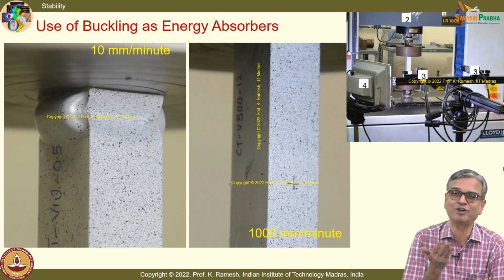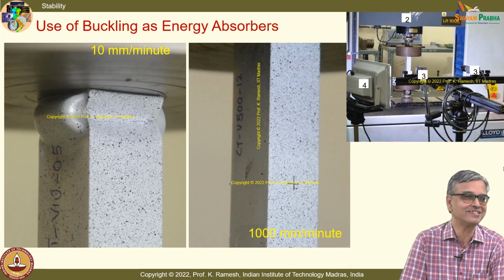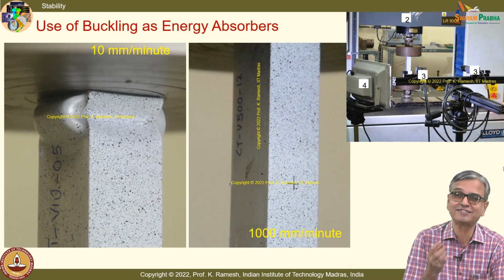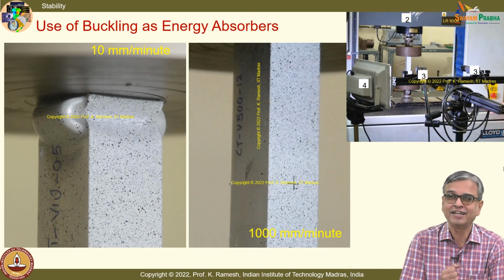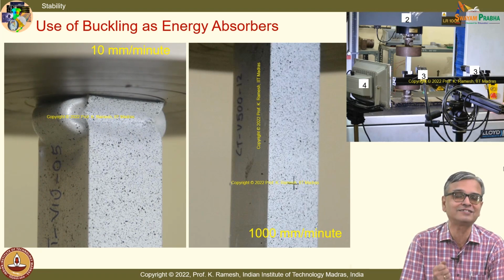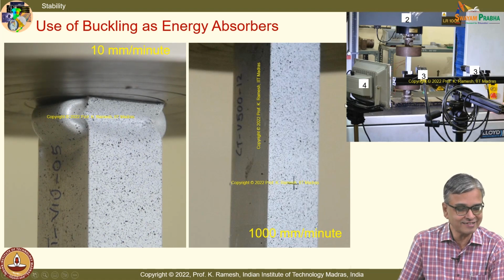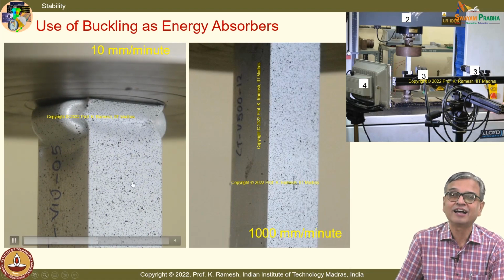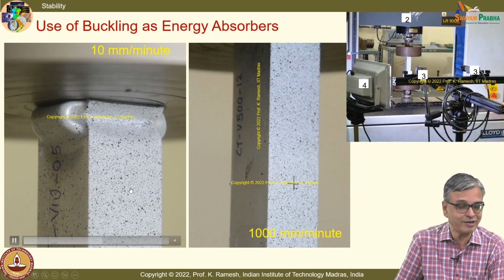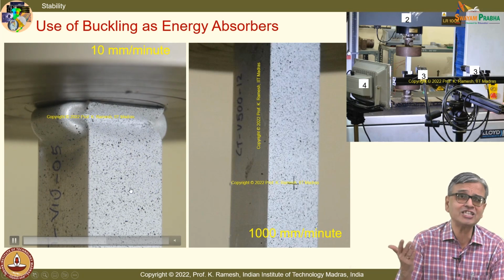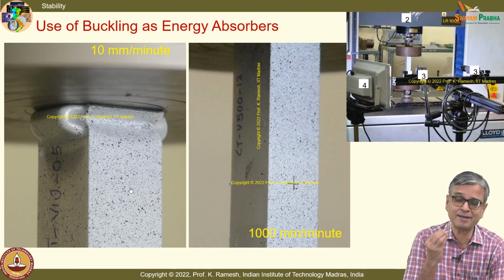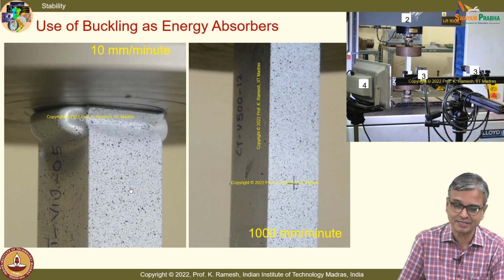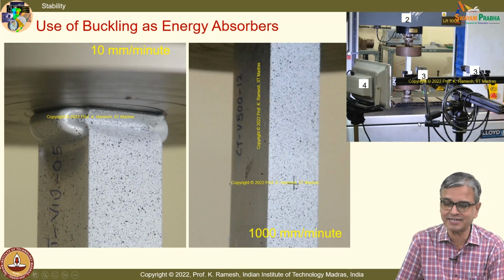DIC. See, I have said you have to be current students, and digital image correlation is the rage now. Once finite element was a rage, everybody was hanging on to it. In experimental mechanics, everybody wants to learn digital image correlation, and this is an excellent candidate for doing digital image correlation, because I am going to have ultra high strains of 30%, and DIC is highly applicable for large deformation problems.